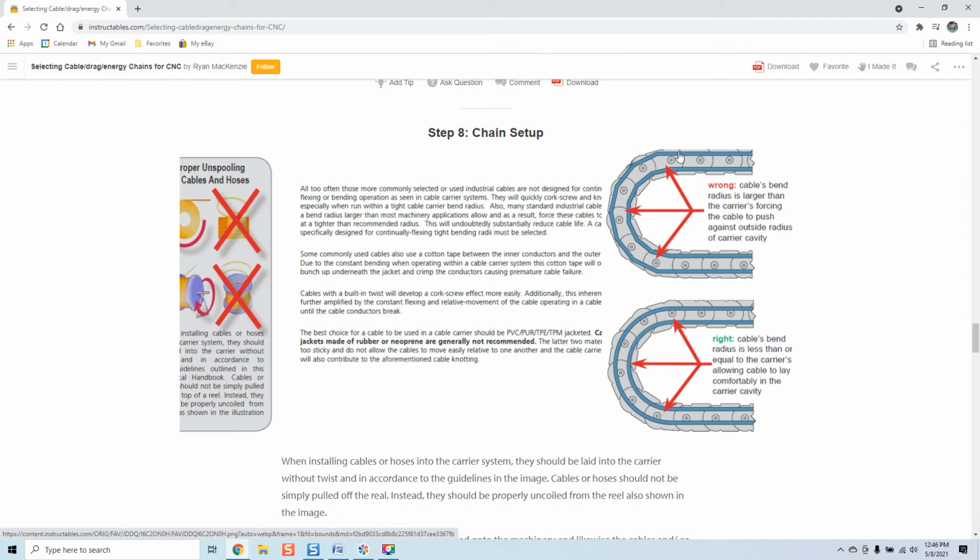So basically what they're saying is, if there's pressure of your cable coming over here and pushing on the cable chain, we don't want that. We want the chain to be actually laying the cable in where it's just around and it's fine. Now, let's talk in terms of logistics. In order to have stress on a cable pressing against the chain, it would have to virtually be jam-packed in here. Most cables from gravity would just sit and flop over.